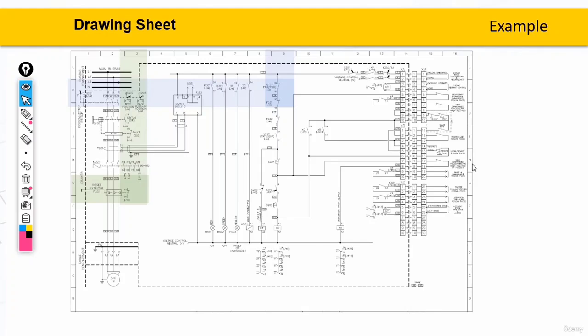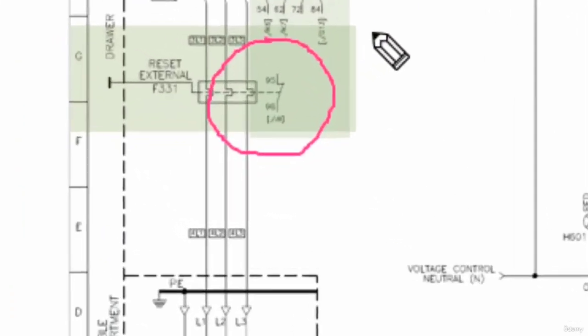Here in this diagram, I have specified two areas for you. The first area would be here, this zone right here. Okay, let me try to mark it a little bit better. This equipment. Also, let me zoom in on it. Okay. Now, the address here would be, let me write it down, 0/J9. Now, this 0 here, guys, means that this whole closed contact, the exact same equipment, has actually been used in another sheet somewhere else.